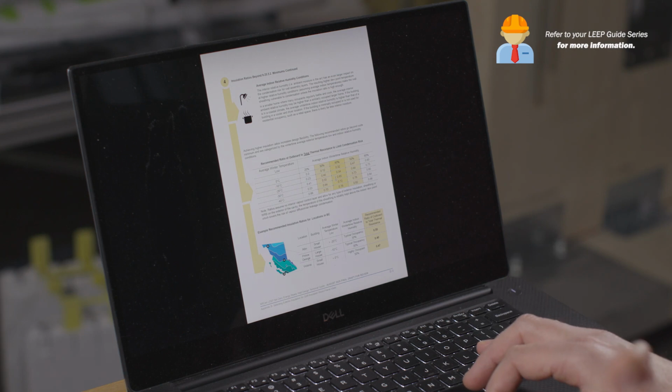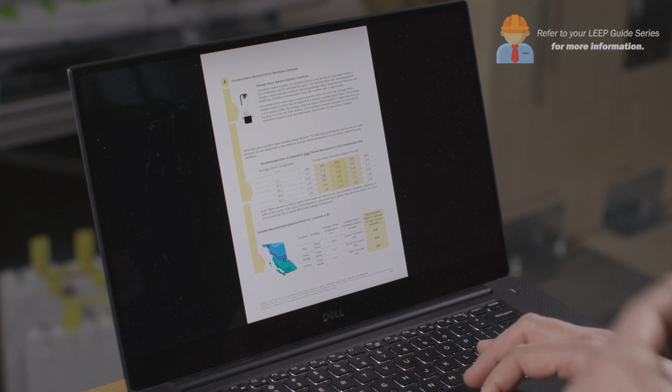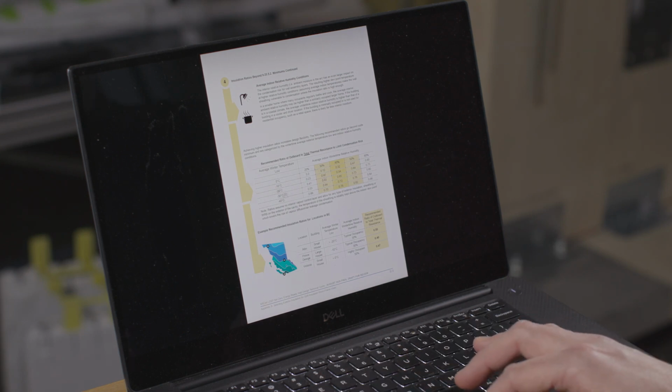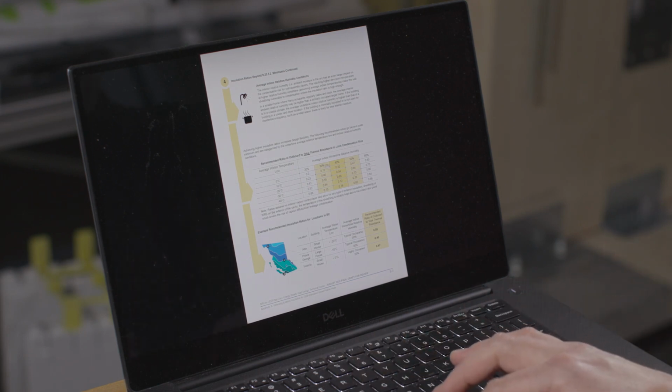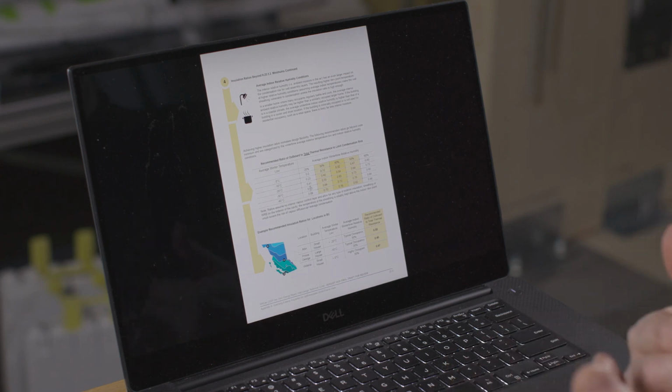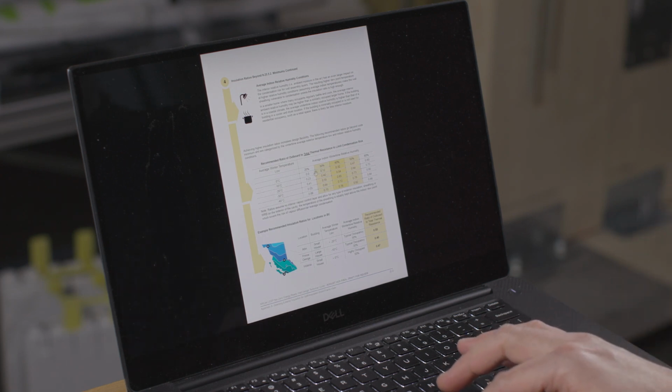Likewise, if I'm in a colder region, the humidity is going to be a bit less in drier parts of the country, and especially when it's minus 20 or minus 30 outside, the humidity is just not going to be at 50%. It's going to be 30%, maybe below 20%. If you're humidifying the spaces, generally it's between 20 and 30%.